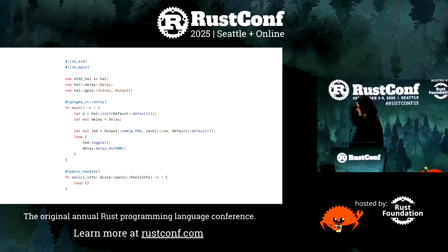Everything else, I think, should look familiar except for down here at the bottom where we define our own panic handler. This is the laziest way to do it. You can just define this in your Cargo.toml and be done with it. Or you can write your own error handling for panics, which is a really awesome thing to be able to do in this kind of project, because when we want to crash hard, sometimes we can write some code that'll make things easier to recover when we want to boot back up.